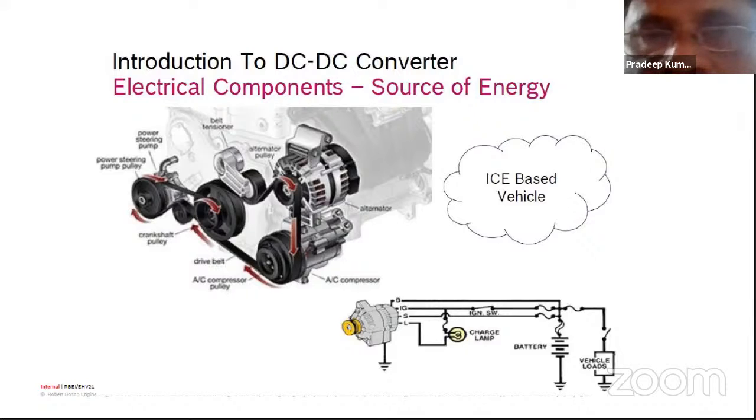Of course, synchronous machines, traditionally, are not self-starting motors. You don't have starting torque in it, but through some control systems called field-oriented control, we can get high starting torque from a synchronous machine. For a large speed range, this torque will remain very high, and beyond a particular speed, when it gets into power mode, the torque starts coming down. I think I have a slide in the coming slides. I'll be able to tell you that.